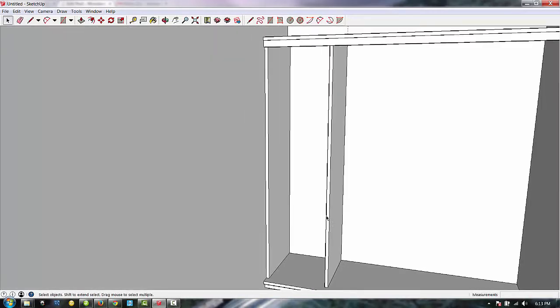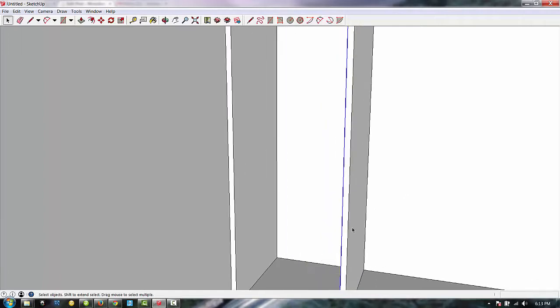So we're going to click on a line and then right click once that's selected and click the divide option. Now you see these red lines appear, and if I don't move my mouse it's just going to segment it the way it chooses to, and then as I move my mouse up you'll see it changes the number of segments just by moving my mouse. I know I want 3 shelves equally spaced, and so I segment the line. So when I click that, it divides this line. Even though you don't see it, it does divide the line.